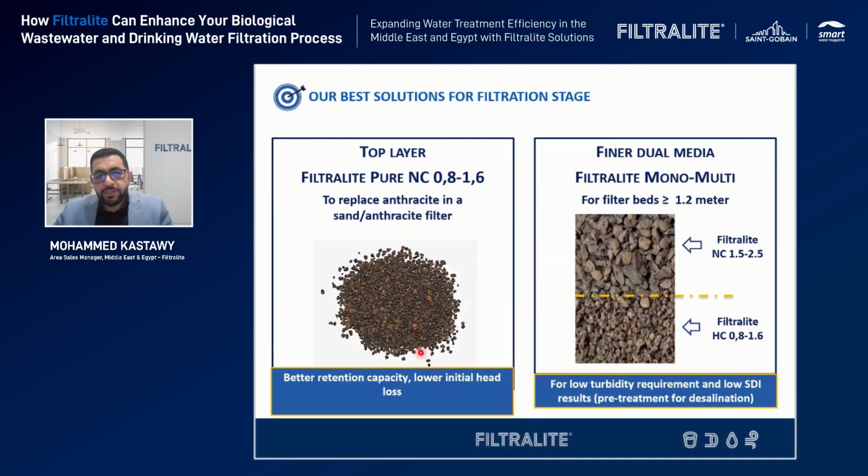There is always a question that comes to me: do I need to use Filtralite always with sand? And the answer, as we can see here in this slide, is no. You can use Filtralite with sand, or you can use it as a single layer or multiple different layers. So it's not necessary to have sand under the Filtralite. And this is an added value for Filtralite.